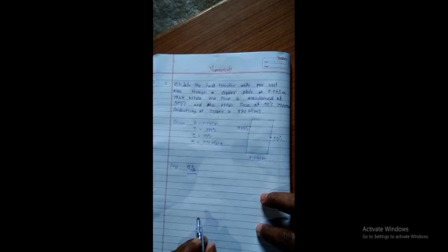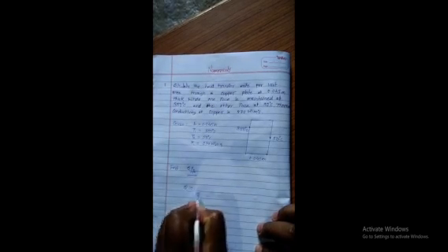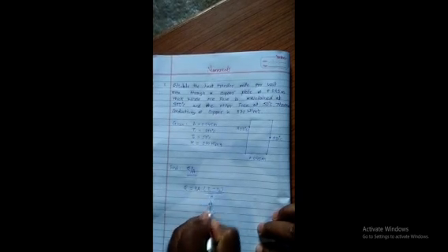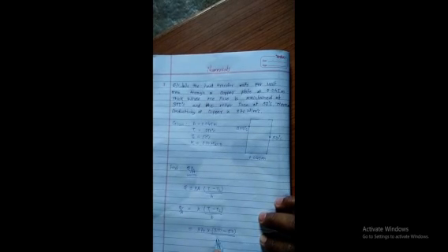Now we know from Fourier's equation for heat transfer through a wall, Q is equal to K A into T1 minus T2 upon B. Here they ask you Q upon A, so it will be equal to K into T1 minus T2 upon B. Put the values of the known, that is K, T1, T2 and B. Here K is 370 into T1, T1 is 350 minus T2, T2 is 50, divided by B. B is 0.045 meter.